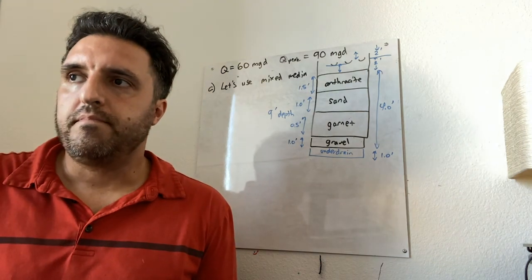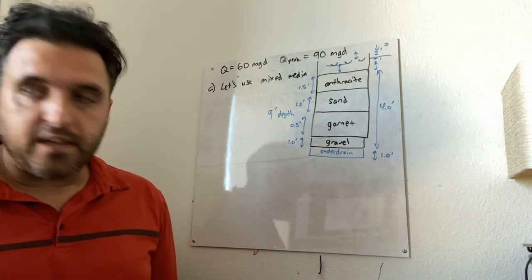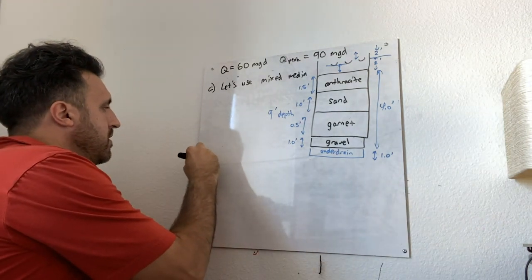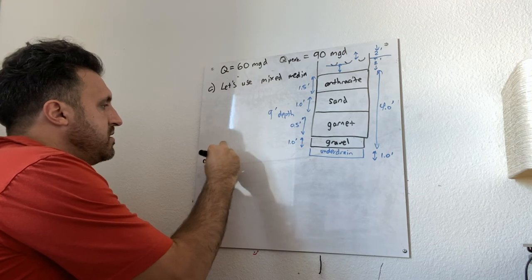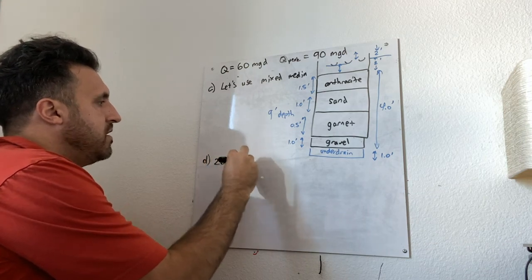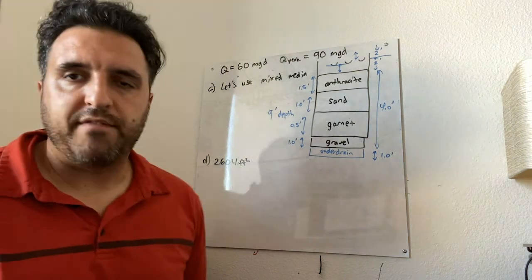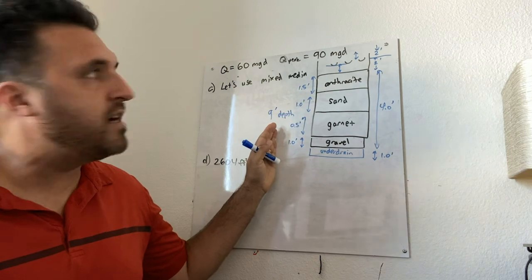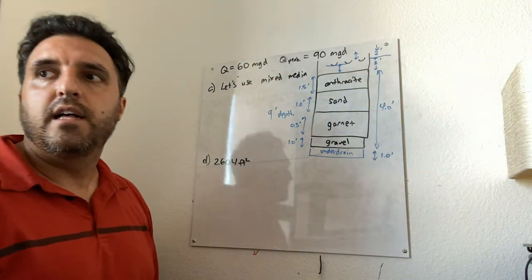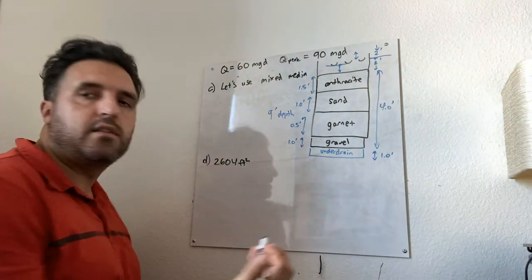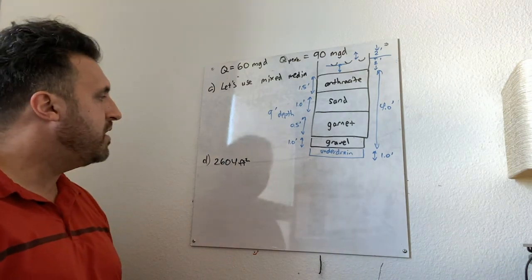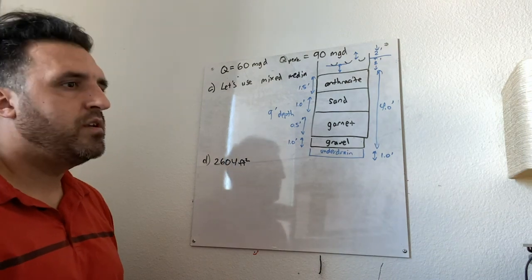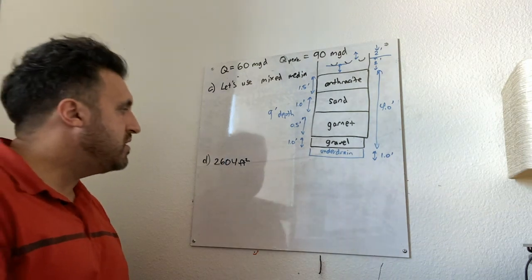So here, again, we've got a surface area that was determined in the previous step. Surface area is 2604 square feet. We'll have to choose a length to width ratio. We've already got our depth set based on our media and the freeboard requirements, etc. Length to width ratio could be up to us as engineers to determine what makes the most sense in terms of constructability and what fits into our site. Let's use a 2-to-1 ratio.